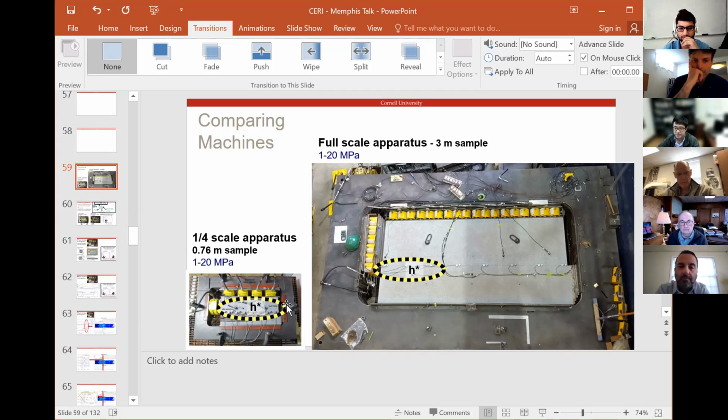In the modeling study, what we did is we started with stress levels that were consistent with the lab, and then to get them to match the field, we pretty much just bumped it up by an order of magnitude. So instead of a peak and residual strength of 8 and 6, we bumped it up to 80 and 60, and we get the same results. So as long as this idea of weakening relationships for friction still holds at a higher stress, which we don't have any reason to believe it doesn't, a lot of this will translate to higher stress. The details may be a bit different.